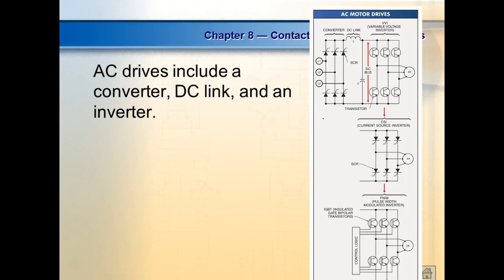What advantage does an AC motor have over a DC motor? An induction AC motor. Oh yeah, AC induction motors are a lot cheaper per horsepower. So now, as far as electronic drives go, the predominant motors are AC. It used to be the only advantage DC motors had over AC motors is speed control, and that's still true.